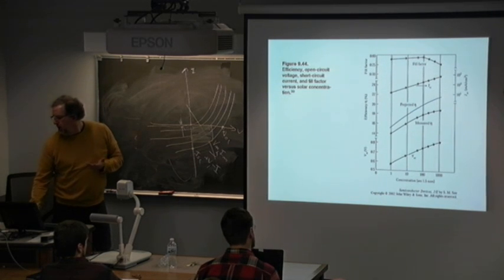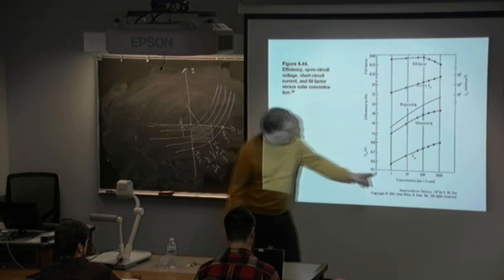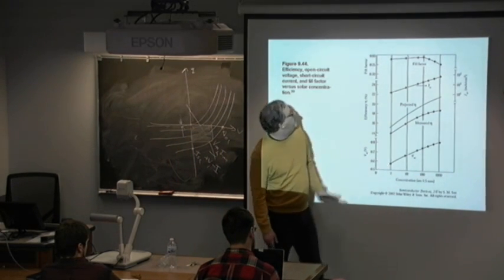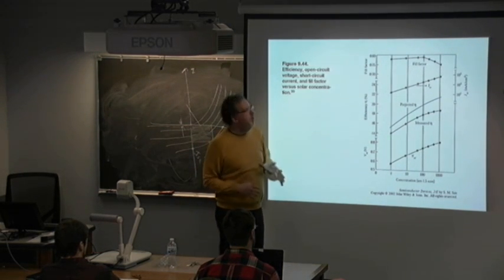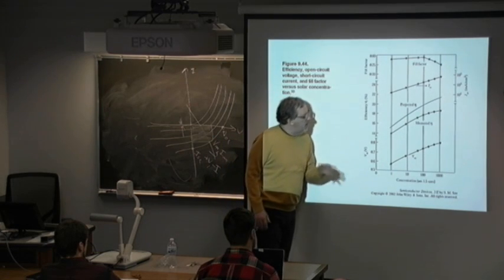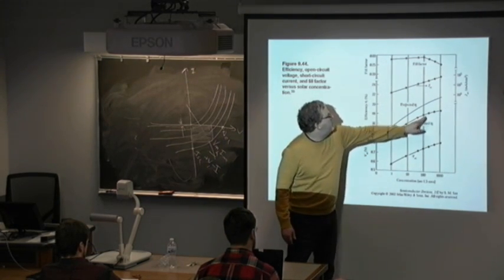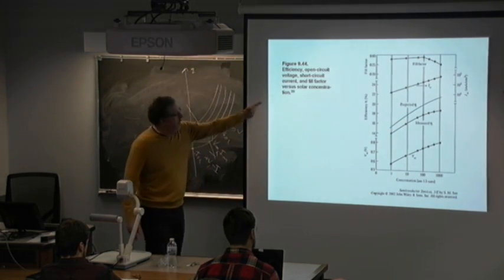And here, as you're ratcheting up the power from 1 sun to 10 suns to 100 suns to 1,000 suns, if you want to use this in a concentration mode, where you're shining a big parabolic mirror onto your expensive solar cell, your VOC can go up and your efficiency can go up, but also, of course, the heat goes up. So you have to water cool these usually.